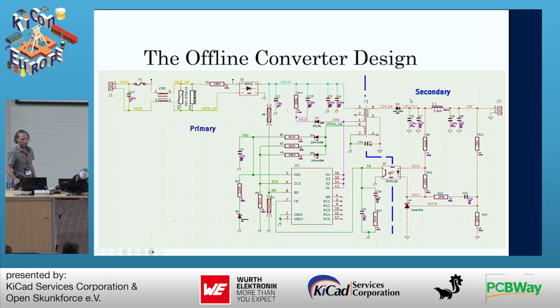where you create a low voltage. And then you need a large voltage clearance between the primary and the secondary side in order to create safety for your 220 volt electronics, so it does not migrate into the low voltage electronics on the secondary side that is usually connected to any user devices. So for safety reasons, by law, you typically need a certain isolation barrier.